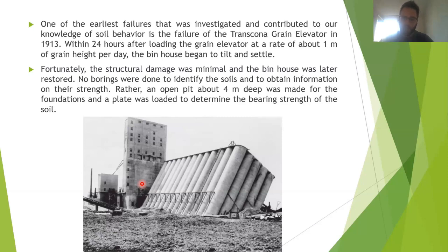So basically, if you're going to have piles that are a meter wide, you need to have at least a 3 meter boring, after you pass the pile length. If you have a mat that can be like 20 meters in width, you need to have like 60 meters of borehole, and that's a good thing because we have laws for it. So the investors cannot do anything about that just because of laws. So you can get really good data, and those things are not going to happen in the 21st century, for sure.